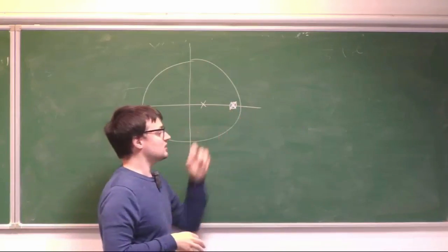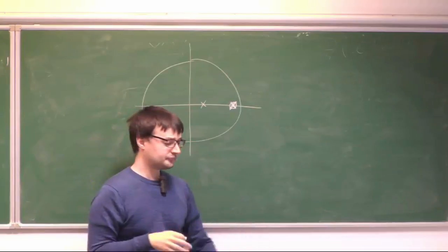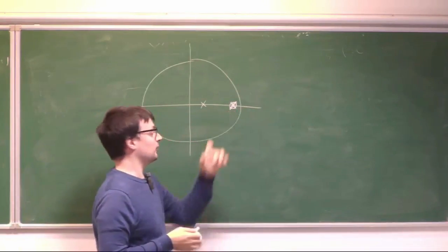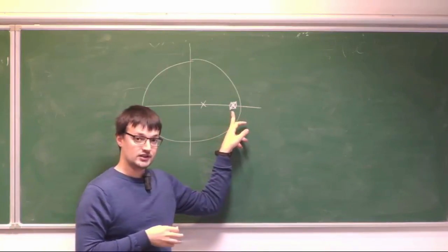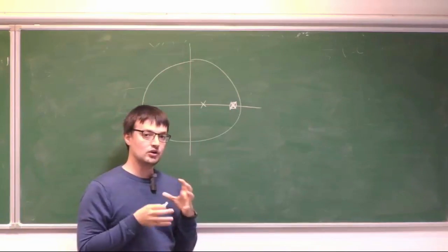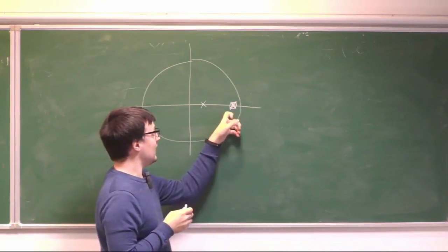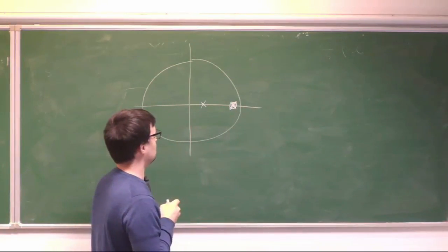This pole that you see here is there because of approximation that you have made, okay? For instance, you are using a zero order hold, and you get this pole over here in your interconnection between the zero order hold and your system. However, the zero order hold is an approximation, or at least how you are studying it, and we will see this in a little bit.